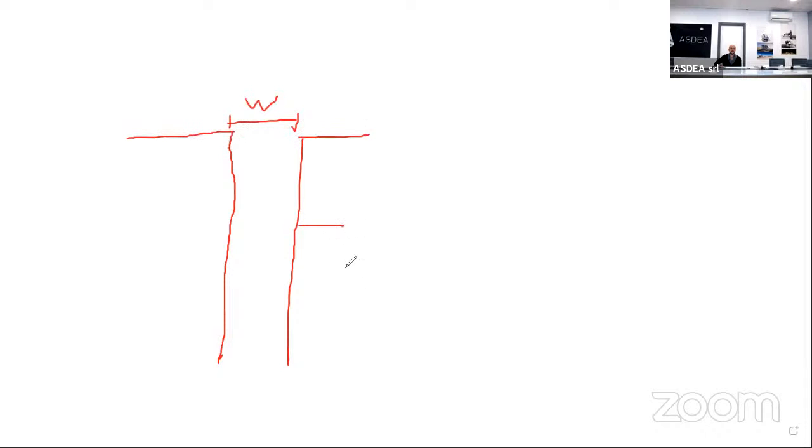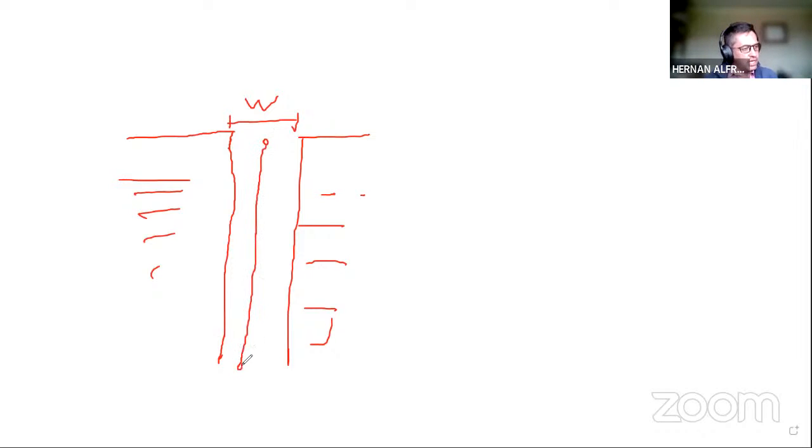Okay, so imagine, let me share once again the screen. So in reality, you have a beam. This one is the width of the beam, and then you have the shell wall here. Okay, so this one is your wall in the other direction, and here you have a column. Now instead of drawing the column in 2 or 3 dimensions as Valentina did, you do it with a column element which has zero thickness. So it's half the width.